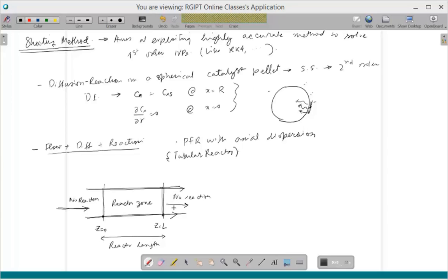So now, although we are going to consider flow, we are going to again think of a very simplistic case, but actually quite relevant, which is plug flow. Plug flow would correspond to the condition where my velocity profile is nearly constant across the cross section.